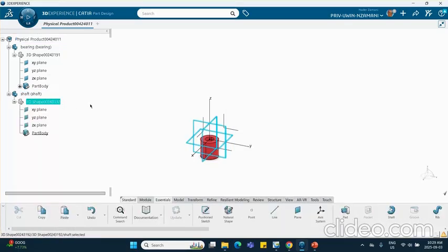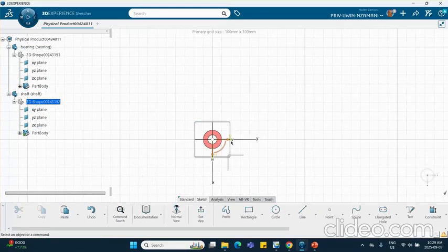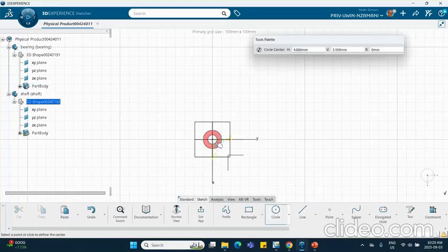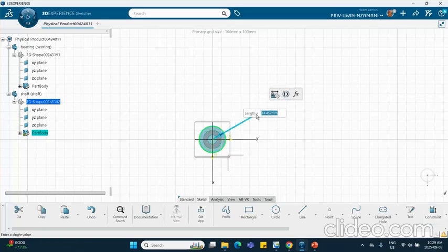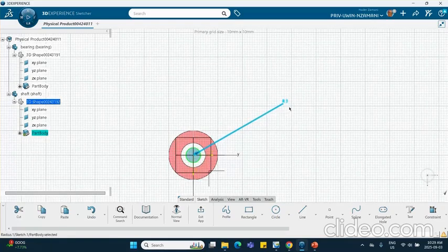Double click on that same horizontal plane. I will sketch. All right, well, I can draw a circle of exactly the same size, or I can project that circle. I'll make it again. So here it is. That is radius 3 millimeters. Good. Sorry, hang in there.